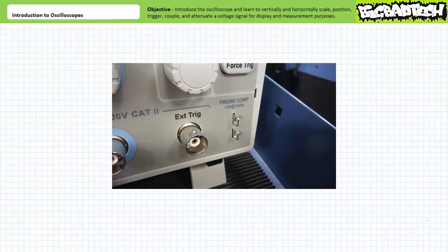Ordinarily, a function generator could be used to create such a waveform. However, the Tektronix TBS 1032B conveniently features a test point on the lower right-hand side that continuously generates this exact waveform. This test point can be used for initial setup of the oscilloscope and demonstration of basic oscilloscope scaling functions. Before we view this test form in the oscilloscope, let's briefly examine an oscilloscope probe.